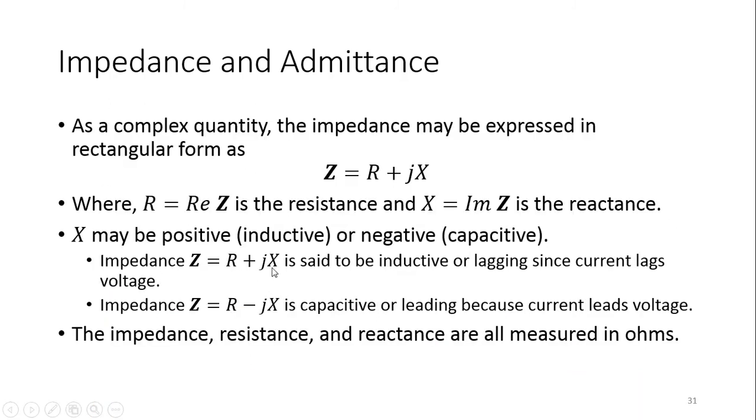So here, if X is positive, then we call the whole load an inductive load, and the power factor would be lagging, whereas a negative X value indicates a capacitive load and the power factor would be leading, because current leads the voltage in that case, as we have seen in our previous lecture and today's slides also.